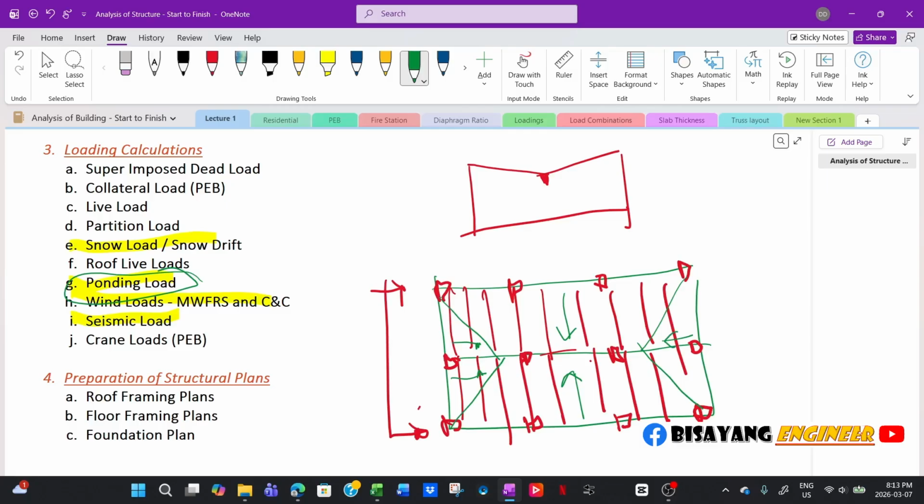Now in that book, the calculation is, for example, you have the initial, because in the climatic information you will get the maximum precipitation in one day. The value there is in millimeters. So for example, where I am now, the maximum daily precipitation is, I think, 89 millimeters. So that's the height of the water, the maximum in a day, per hour.